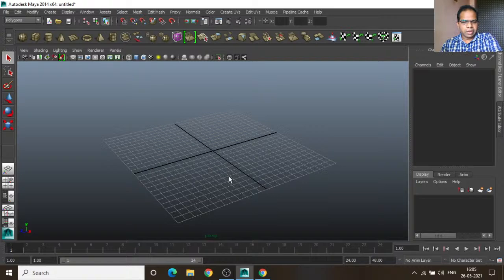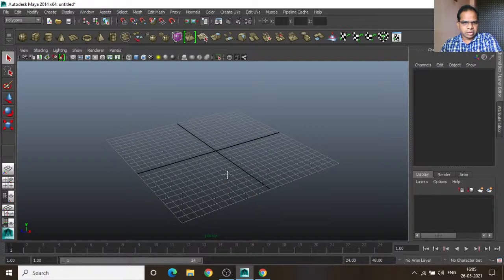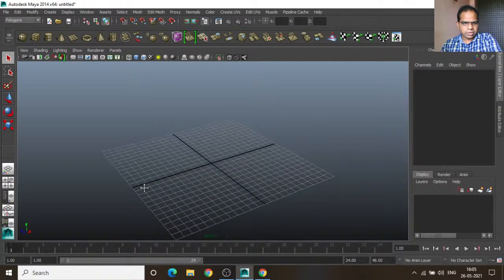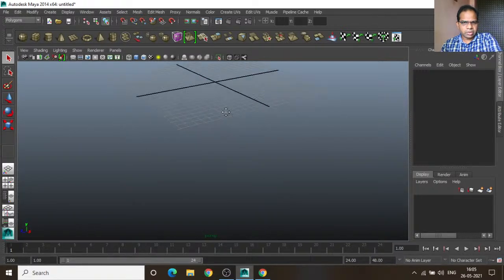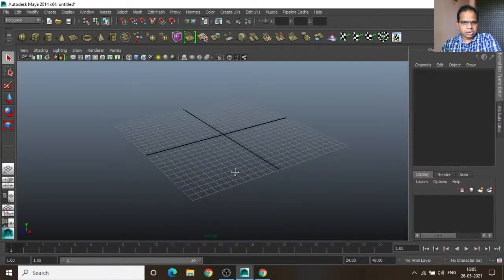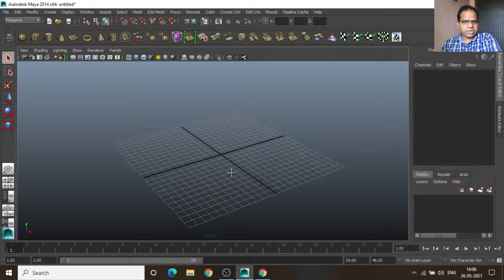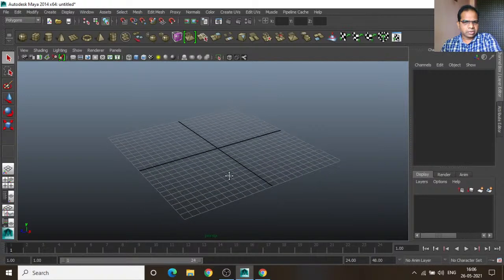In the same way, keep pressing the Alt button on the keyboard and click the middle mouse button, and immediately the cursor changes like that. So these are translations: left, right, top and bottom. So it translates in the x direction and y direction.